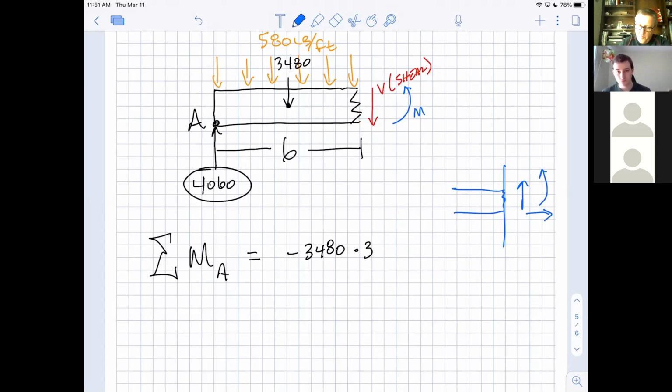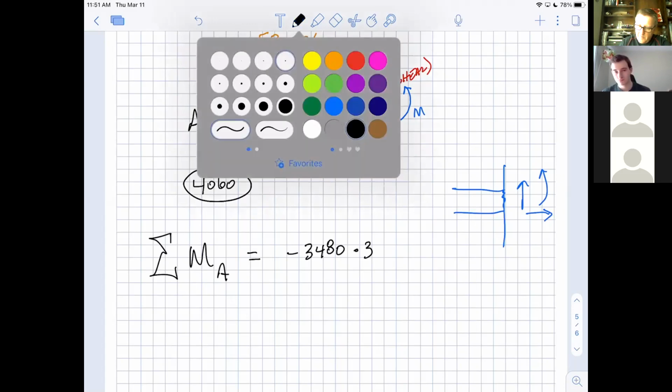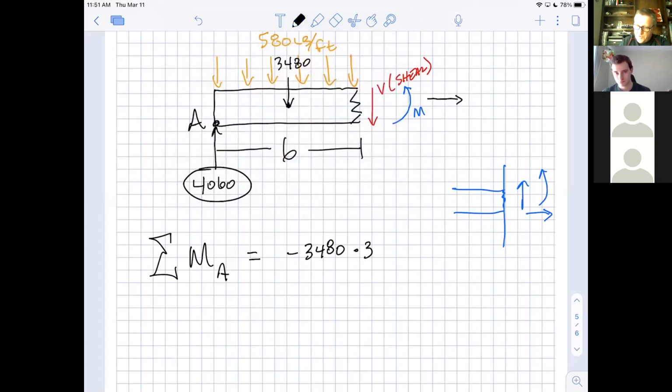So this is a fixed support. I'm going to go ahead and draw that in. A lot of times this direction is called normal because it's perpendicular. It's no different than a fixed support because it's fixed. So it's going to have all of those. It's going to have a force in Y component, a force in X, and it's going to have a moment. Thank God that's there, because that moment is what keeps this beam from breaking, if it makes sense to you.